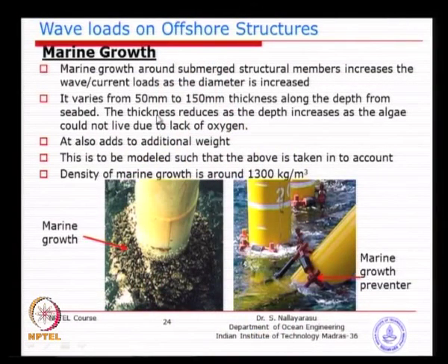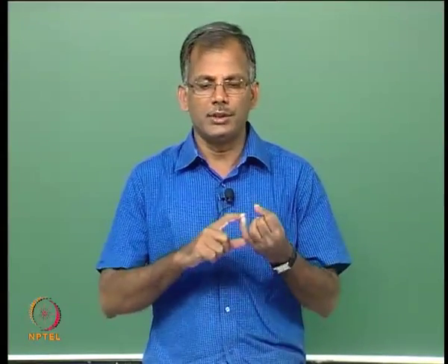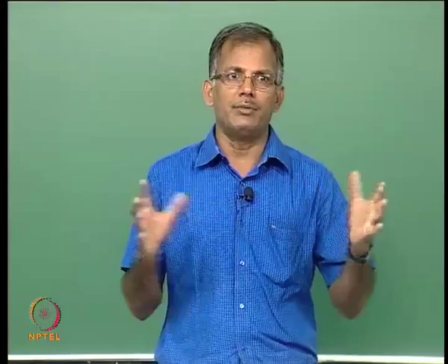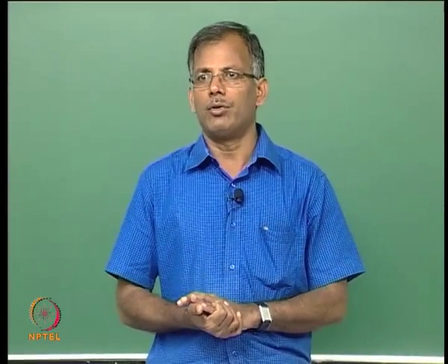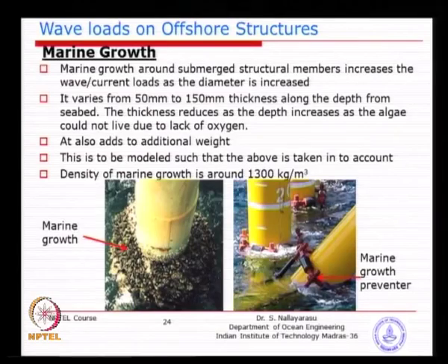So, if you look at this, marine growth is a phenomenon which cannot be prevented. Number 1, for sure you can't prevent it, it is going to grow, and then how we take it into account is something that we need to think about, because the diameter increases, but it is not going to offer structural strength, it is only a burden for us. It increases the weight, it also increases the dimension which will capture more wave and current loads. So, that means we need to consider this as a separate item in the hydrodynamic load calculations.